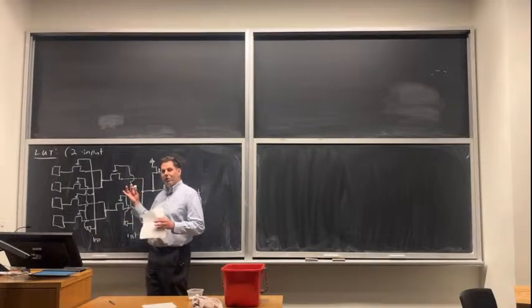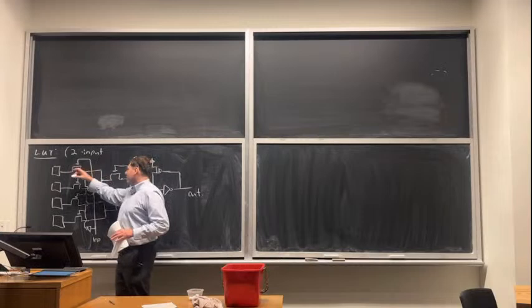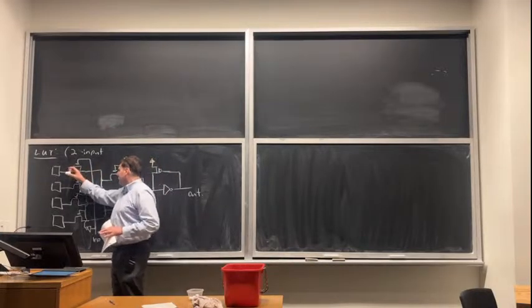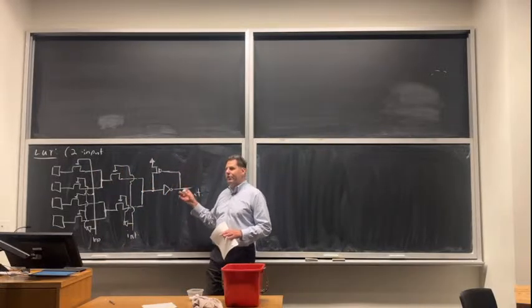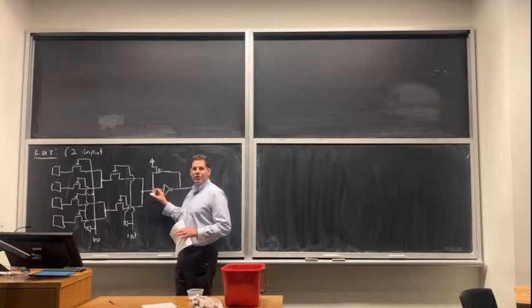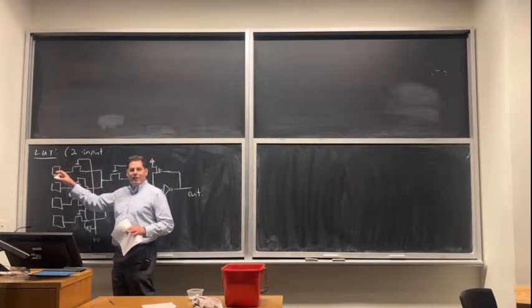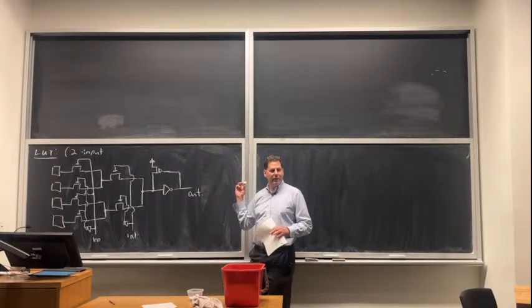And it'll be slow because these pass transistors, connecting 2 transistors in series like this, if you think of them as resistors, which is to first order correct, it's like you've doubled the resistance, all right? So the more pass transistors you have in series, the less capacitance you want loading them because they're going to charge and discharge that less efficiently. So I want to have this inverter here so that I'm isolated from whatever I'm driving. So that's the first thing.